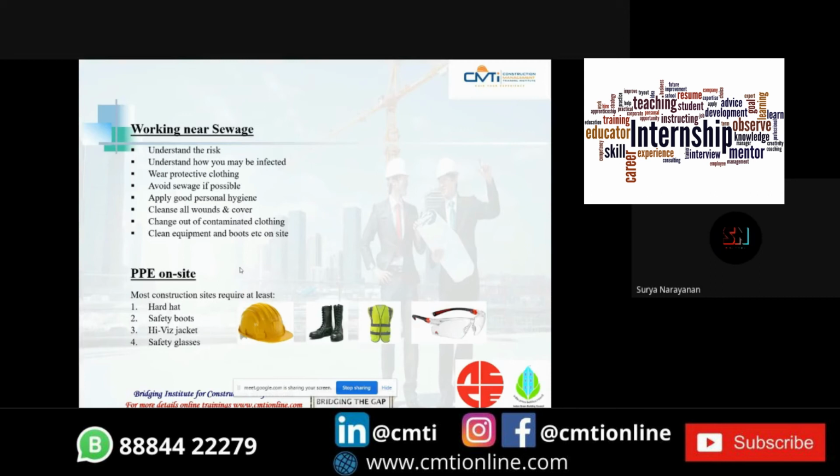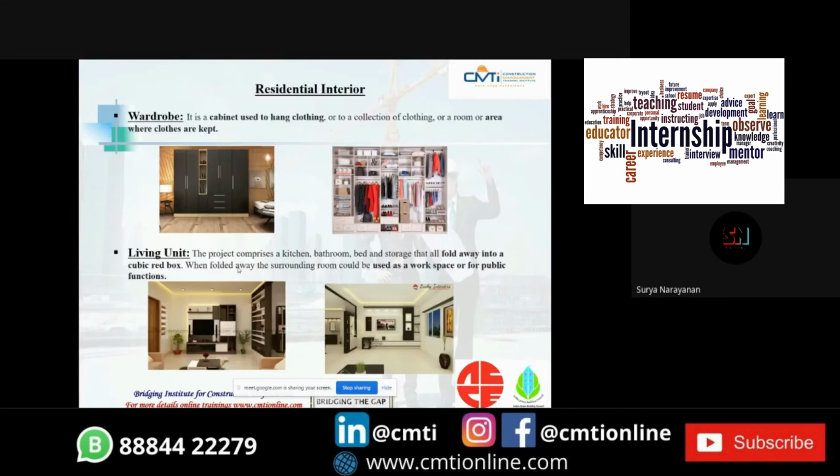So PPE on sites, where PPE stands for personal protective equipment, and these are the basic requirements while working on a site: hard hat, safety boots, high-vis jackets, safety glasses, and nowadays masks are also very important while working on a site.